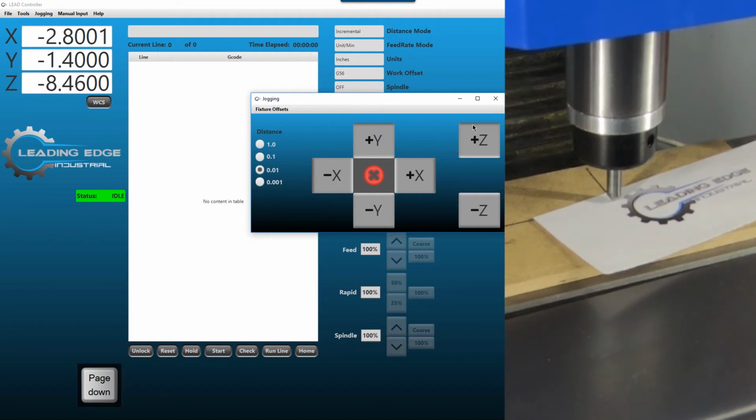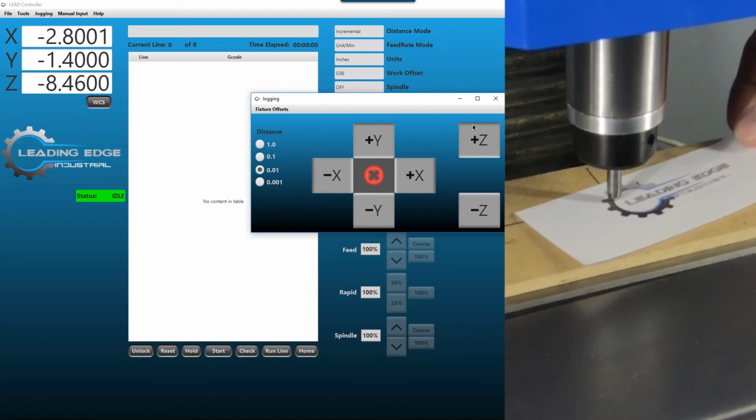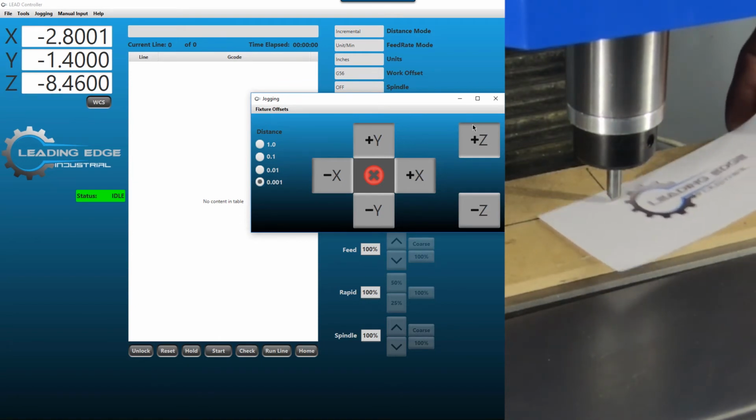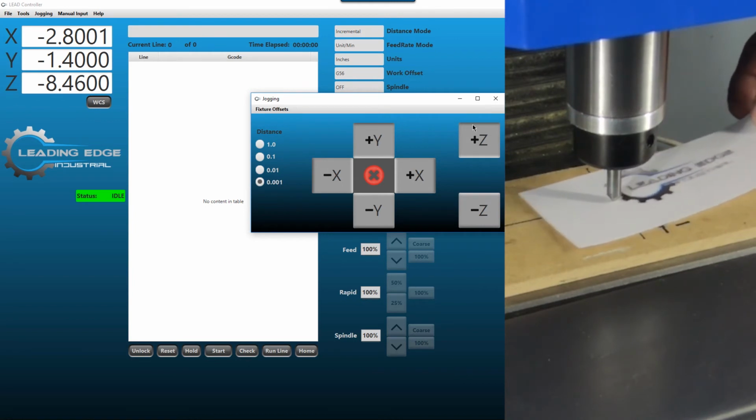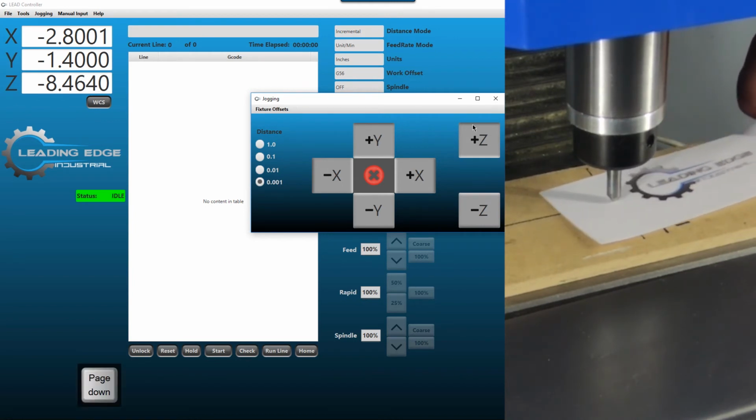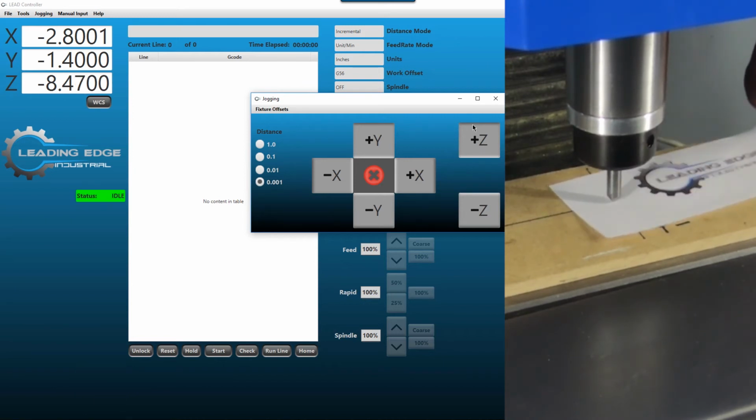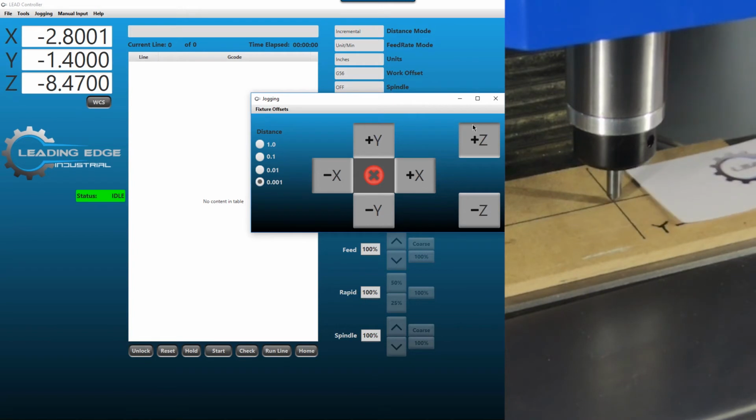We're probably pretty close there. Now we're gonna switch over to 1/1000 of an inch by hitting our divide key, and we'll just move the piece of paper around and hit jog down until it just grabs that piece of paper. Right there, you see? So now we can still pull the piece of paper out without tearing it, and now we know we're 4/1000 of an inch above that work piece.